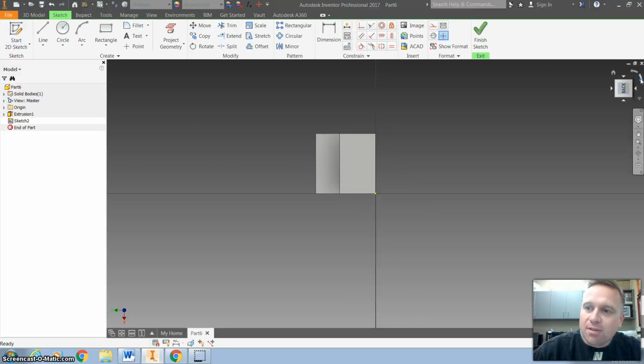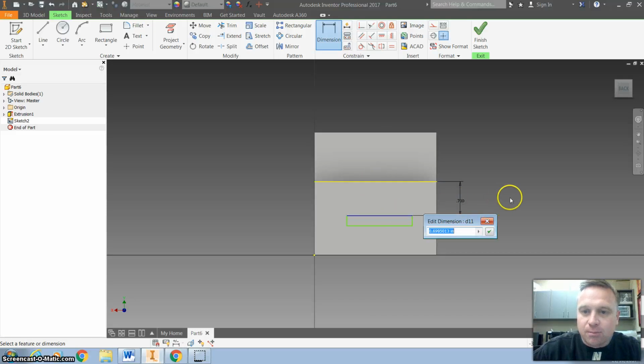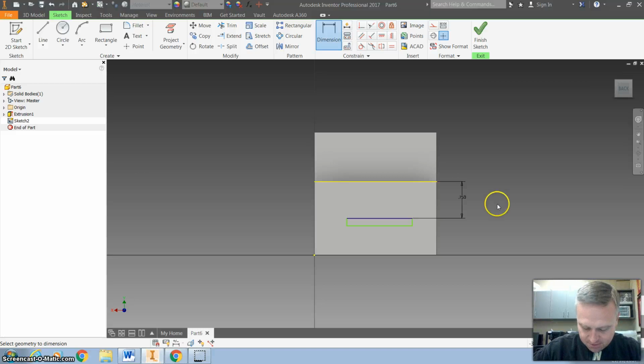When I have that, I'm just going to click this arrow to orient the view the way I want. I'm going to grab the rectangle tool and draw a rectangle on the object. In this case, all of my dimensions are green, and so I just made it the approximate size of the object. Once I have that, I can go ahead and add some constraints to it. I'm going to add some dimensional constraints in this case. I click to place the dimension, and I can type in the dimension I want. So I want that to be 0.75.